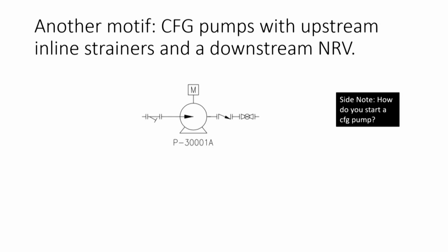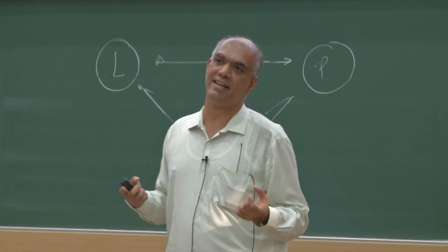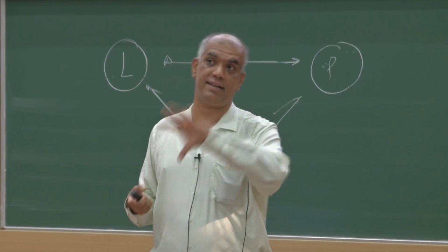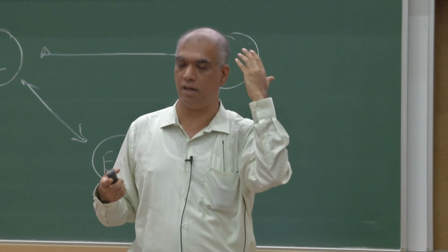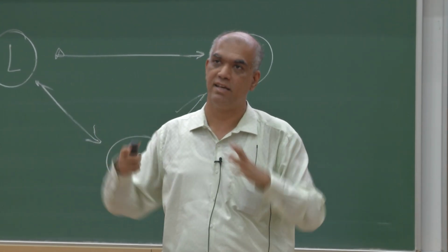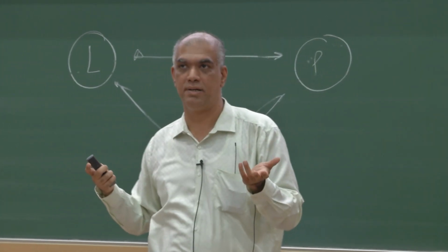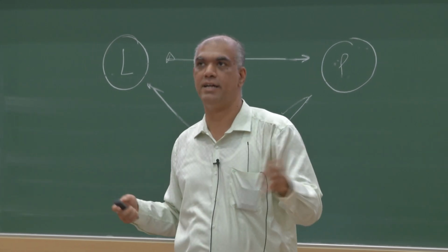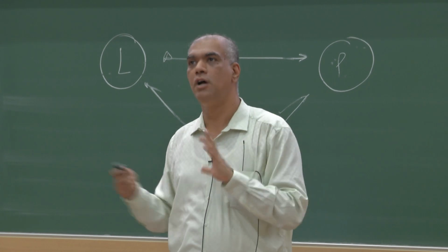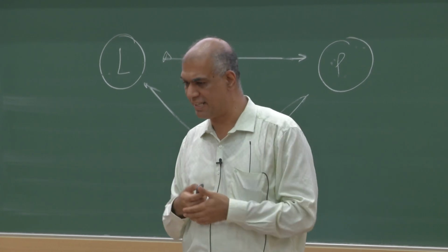So many of the pumps, what you see on and the symbols, I'll show you a PDF that you can look at later. Like engineers communicate with a common language, and for chemical engineers, this is standard symbols that go into a P&ID. So you don't need to remember them all, but start using standard symbols, because if you have something else for a pump, and this I've seen in a lot of reports, you have a distillation column, but they say distill and a circle, and somebody who sees it will assume it's a pump or something else, or a storage sphere, and then they find out, oh, that's a pump, right? So avoid that by sticking to standard symbols that, like here, the M is a motor, right? Anybody who sees it knows the M is a motor, whatever. So stick to standard symbols when you're doing these things.